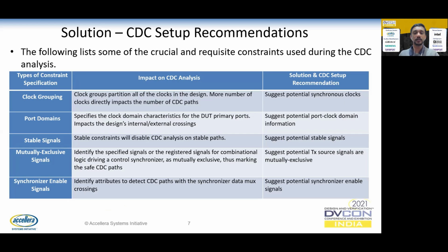Solution to CDC setup recommendations. In the following table, we have listed some of the crucial and requisite constraints used during the CDC analysis. Corresponding to these constraints, we have captured a high level description of what impact these constraints would have on the CDC analysis of a design.